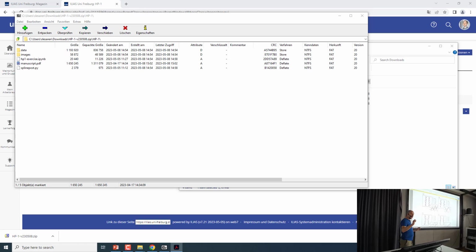But then we have random preferences in the shapes, and our system generated multiple solutions with Poisson ratio very close to -2, but with completely different geometries. And that's quite fun. So right now, we have a tool that allows us to have this variability in our design while keeping the property the same.